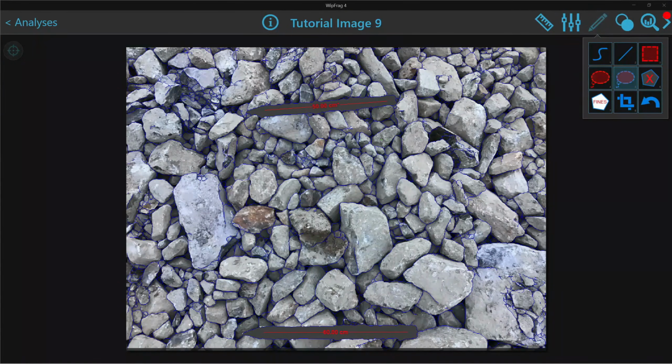Lasso Delete plus Outline combines Free Draw and Lasso Delete. This tool will also close itself back on the starting point and any net within will be deleted. However, the path that was drawn will turn into net. Ignore Block. Click on any particle or area of the image you wish to ignore. This will ignore the marked particle from the results. Click on the same spot or use the Undo tool to remove the ignored particle.